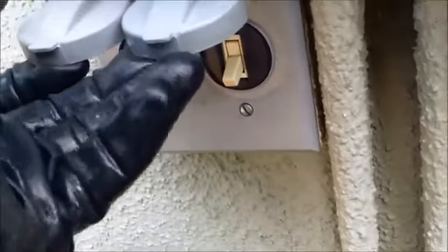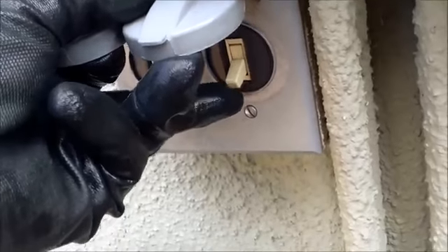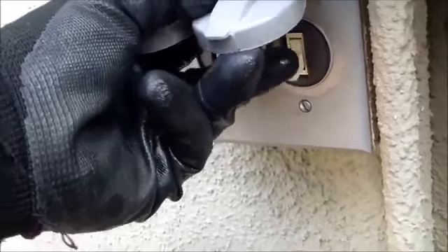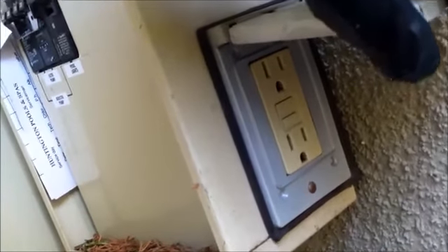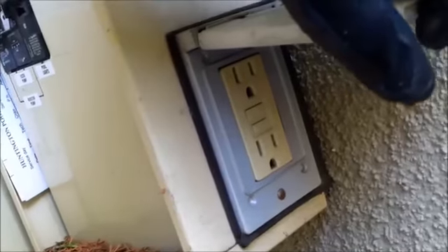Go to turn on the pool or spa light and it's not working. Definitely check the GFI attached to the light itself. One thing that happens with your pool lights is that the GFI will trip and they won't work, so you just simply reset the GFI here, and that should get the pool lights working again. Sometimes the bulb itself is burned out, but usually when the spa and pool light are both out, it's the GFI that's the problem.